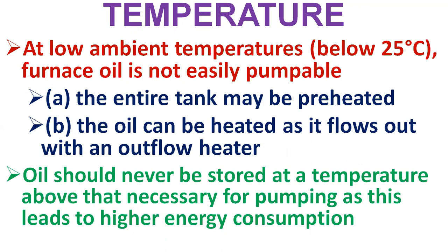To reduce steam requirements, it is advisable to insulate tanks where bulk heating is used. Bulk heating may be necessary if flow rates are high enough to make outflow heaters of adequate capacity impractical, or when a fuel such as LSHS is used.